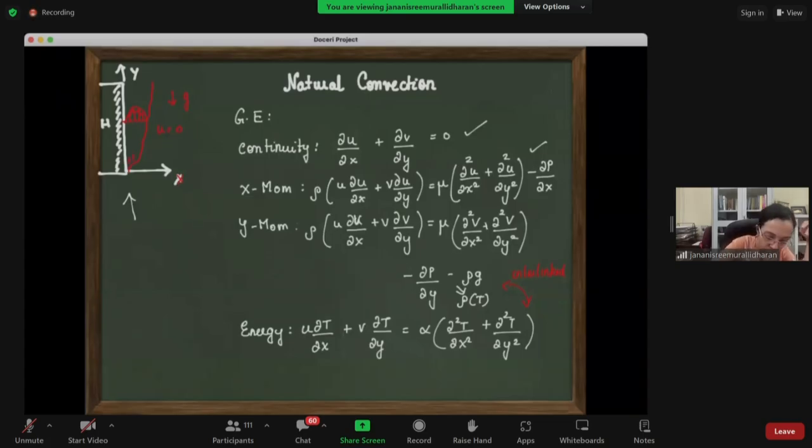So flow is going to start flowing up here. And after the heated plate, it will lose energy. So it will probably just circle around, lose the density difference, and probably drop down. So there is a convection current that is set up, right? So that will go typically like this. And this is purely density driven, correct? So you are going to get a boundary layer of sorts where flow is flowing.